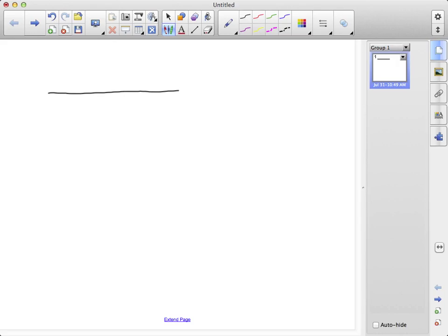Let's consider a straight beam supported at its ends and subjected to some combination of downward loads. A beam made out of a real material will flex under these loads. We could sketch a set of cross sections on the unloaded beam, and they would all be parallel to each other. In the case of the loaded beam, each of those cross sections rotates with respect to its undeformed state, and adjacent cross sections are no longer parallel to one another.